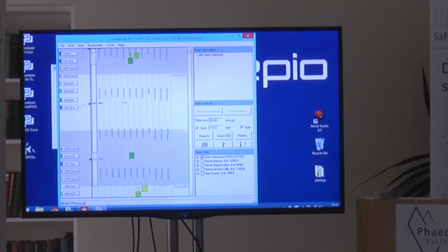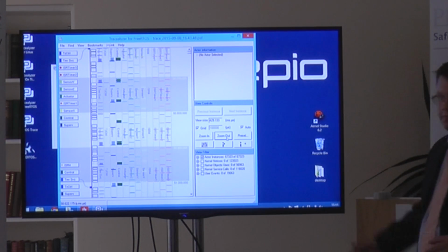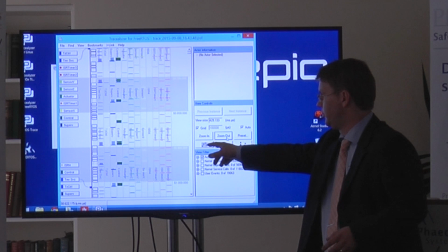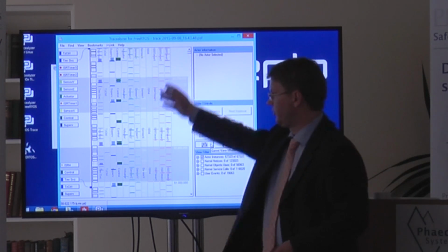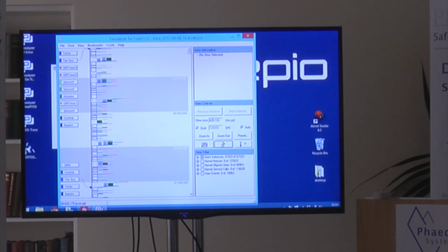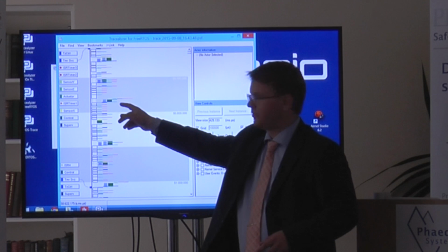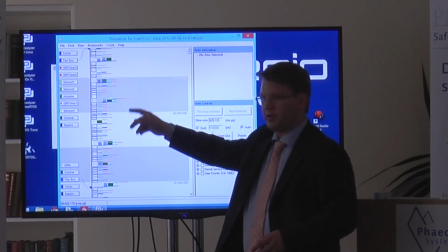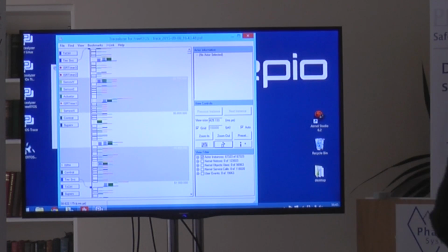As Mike mentioned, we have this main view with task scheduling and interrupts. This can be shown in different ways. We call them view modes. You can easily switch with these buttons. This is the Gantt mode, where you have one column for each interrupt or task. But if you have a lot of tasks, you can use this mode instead, where you get a kind of stacked view. And then you see the spikes here, where you have a lot of tasks being activated at the same time. So if you zoom out a lot, these spikes will still be very clear.